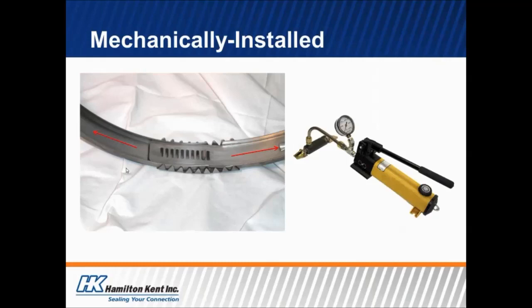So the one thing that's good about this one is that it can't be messed with in the field, so that if there's anything the contractor wants to try to do, he's not going to be able to do that without the precaster knowing about it. The downside is that these jacks are relatively expensive, and they do require occasional maintenance. And if you do need to make an adjustment in the field, then it means you have to take that jack out to the field in order to make that adjustment.